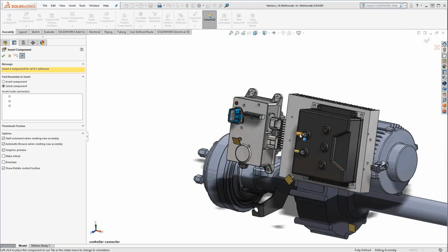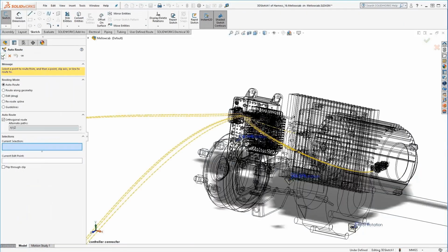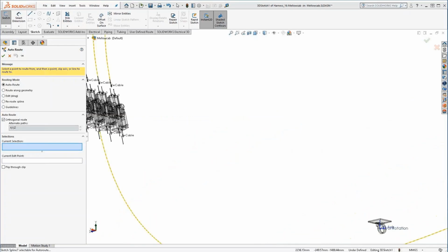Okay, so once this relationship is done, I've got everything I need for asking SOLIDWORKS to go and route this for me. Start joining pin with pin from this connector to this connector, and it's ready for that. Okay, so now it's finished. I've got all the connectors linked with the information from the Excel. I may change the size or whatever, but if I accept, I get these guidelines, these yellow guidelines you can see here. This is a preview of the connections.